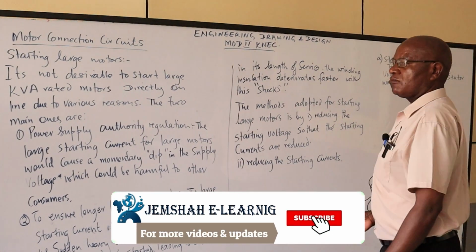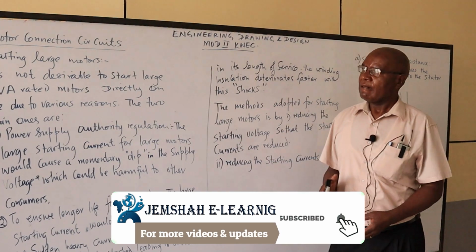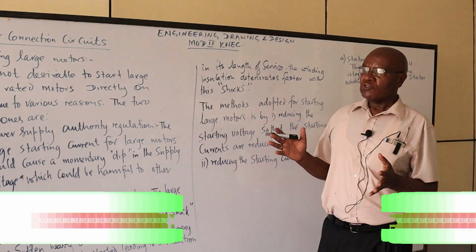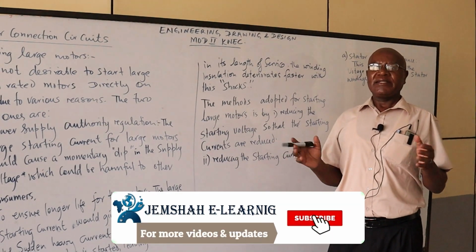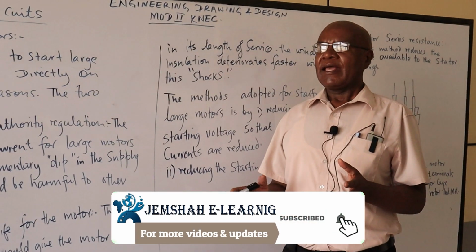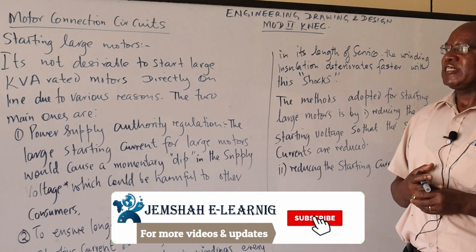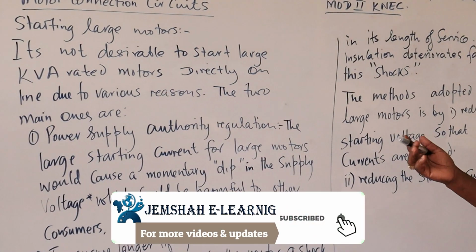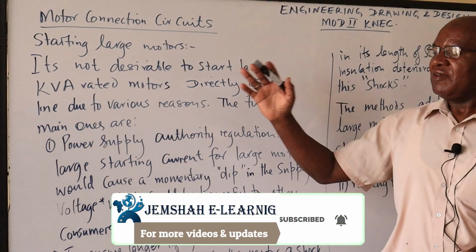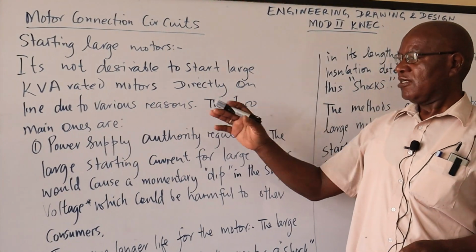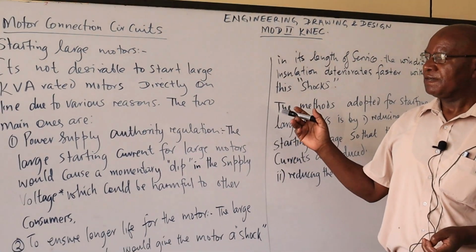Now, in our last lesson, we did the DOL circuits, and those motors could be connected directly online. And now, today, I want us to start with how we connect large motors. Now, it's usually not desirable to start large KVA-rated motors directly online due to various reasons.